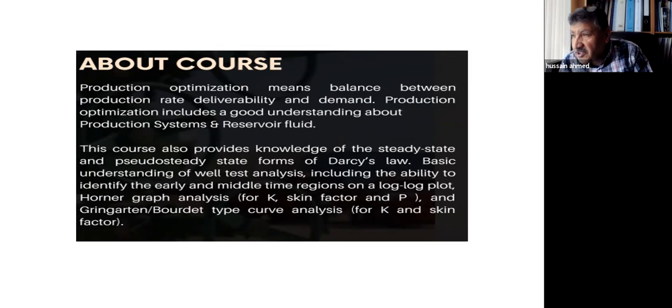That needs from you to understand the Darcy equation. How does a steady state flow or pseudo steady state flow, radial or spherical, linear, whatever, you need to understand the Darcy equation in order to get that optimization. So I will touch on the Darcy equation almost every day and explain the application of it and the problems we face. Challenges we face in production include what we call formation damage. Formation damage can affect the productivity and also the production, which we could face later on.